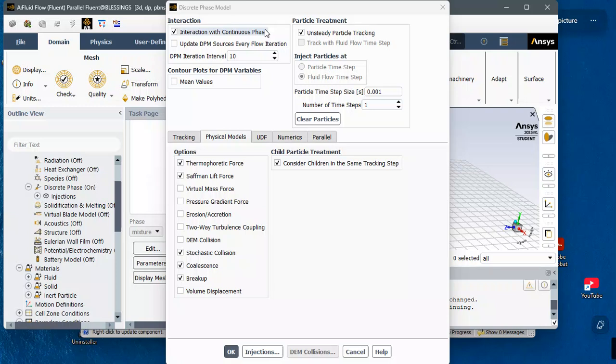You mix them and see the behavior at the outlet. If at every point there will be air and water throughout your system, you pick this interaction with a continuous phase, because you have two elements, let's say air and water. Even at the outlet there will be air and water, so you need to set that these two are in a continuous phase.